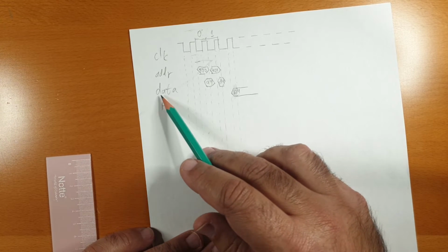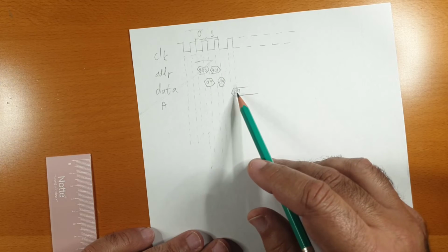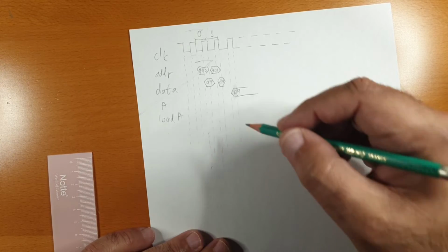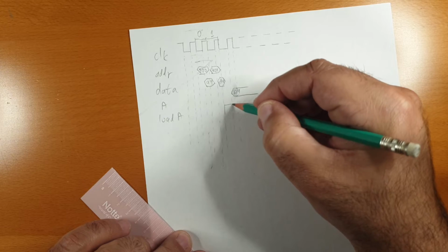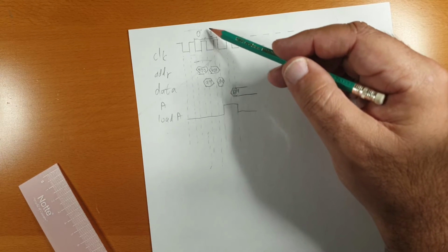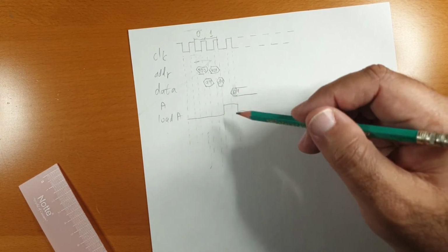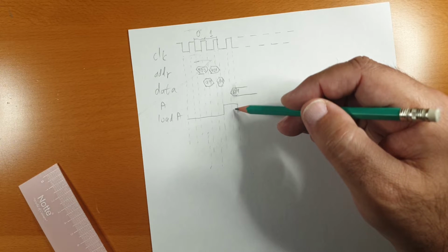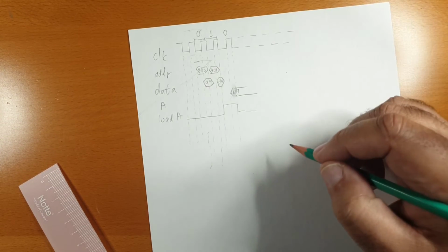So let's start with the accumulator load control line. This control line tells the accumulator to read its input from the data bus and load it into the register. Since the control lines update on the falling edge of the clock, we need this line to go high here. Since the control line is latched, that means that on cycle 1 of the load A command, we need to tell it to raise the load A control line, which will cause it to actually go high on the first cycle of the next command over and load the accumulator 1 cycle into cycle 0 of the next command.